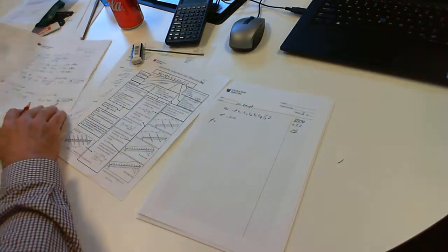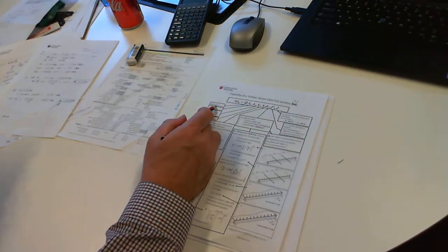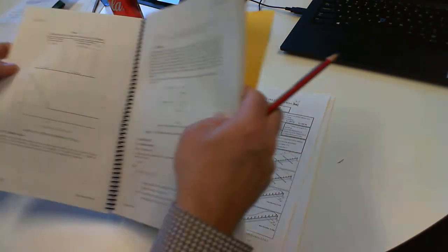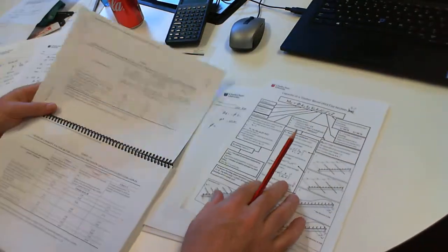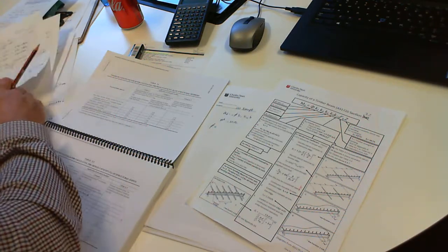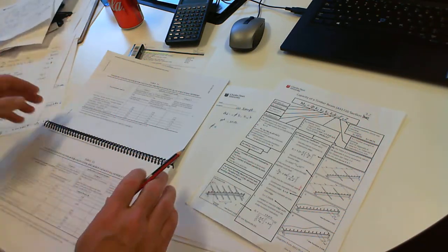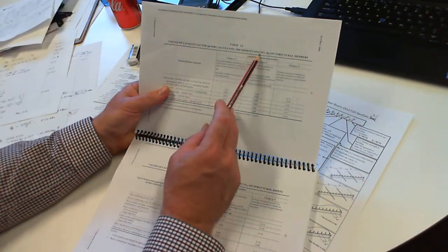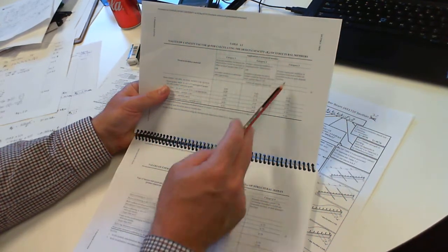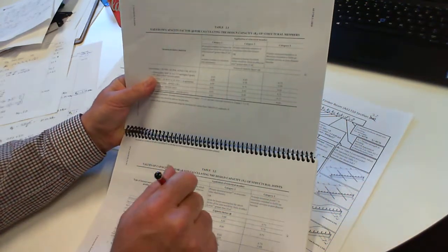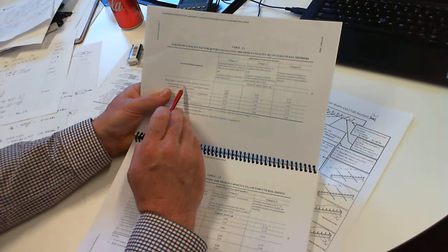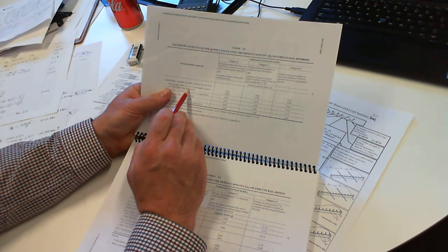Phi comes from table 2.1. So open our code to table 2.1. Table 2.1, value of capacity factor for calculating design capacity of structural members. So this is bending and axial force and that kind of thing, and this is the joints down here. So we're up in this table. Stress grades, MGP 15, no. All other timber grades, here we are.